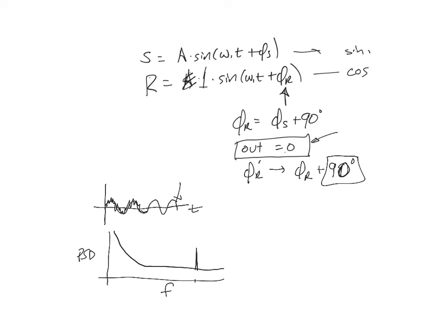And there's a neat way of thinking about this, which is that the time constant kind of sets a window around which I accept signals around this frequency right here. And there's a delta f right here. And roughly speaking, the delta f, just by dimensions, is equal to 1 over tau. So this is another way of looking at the question of how long should I set my time constant.